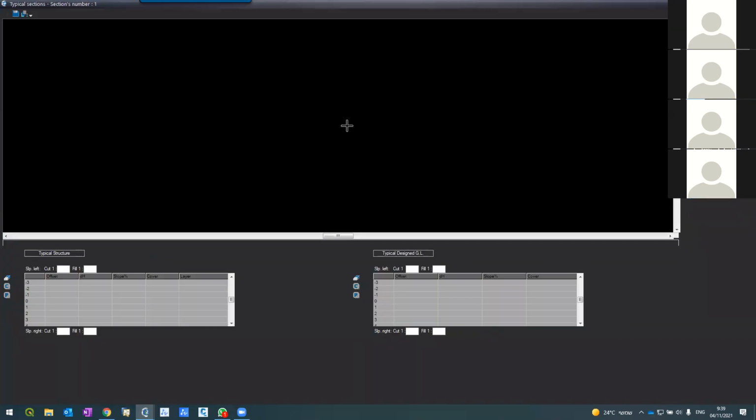Okay, this is the extract. It's very similar to the cross section. You see, there's a window here, table here, table here. Please listen carefully. First of all, I'm using one template. If I have several templates, then I have to create different segments. These are lists of segments. In this case, I have only one segment that goes all along the road from 0 to 486.